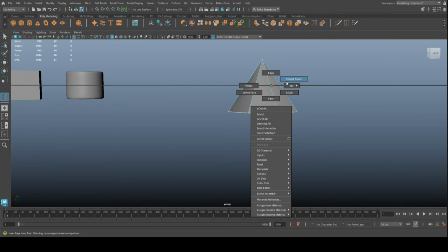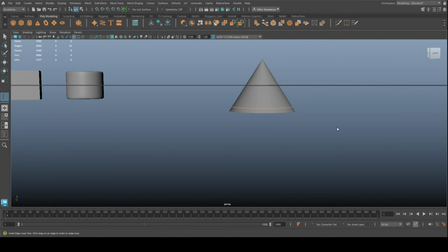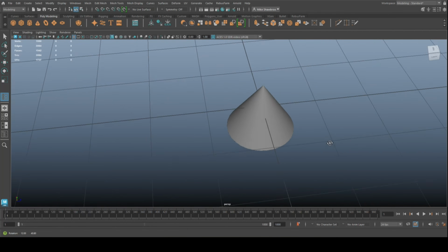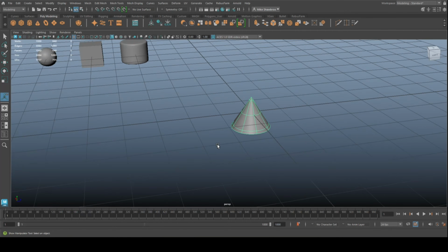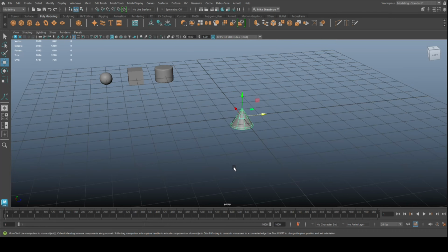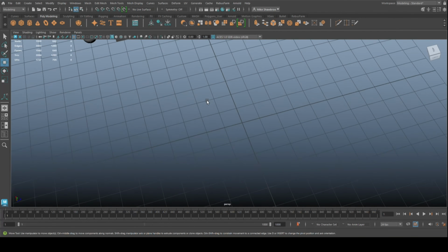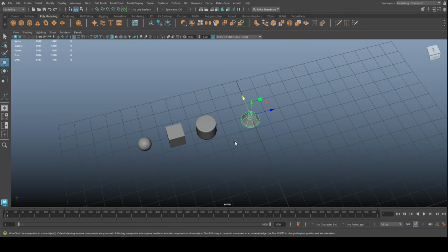Like this. Okay, there you have it. What you can do is select this guy, go to mesh and smooth instead of preview smooth, and you're good. Hit W, hold on X, move it over here, and we'll move it over a little bit in this direction.